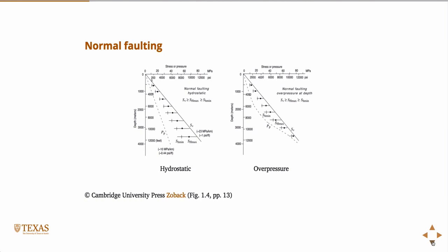But essentially, you can also estimate that in terms of hydrostatic. What I mean when I say hydrostatic is as if it were a column of water, a solid column of water all the way up. Right? And it turns out that that's about 0.44 psi per foot. Right? So that's two lines that give us the upper bound and lower bound.